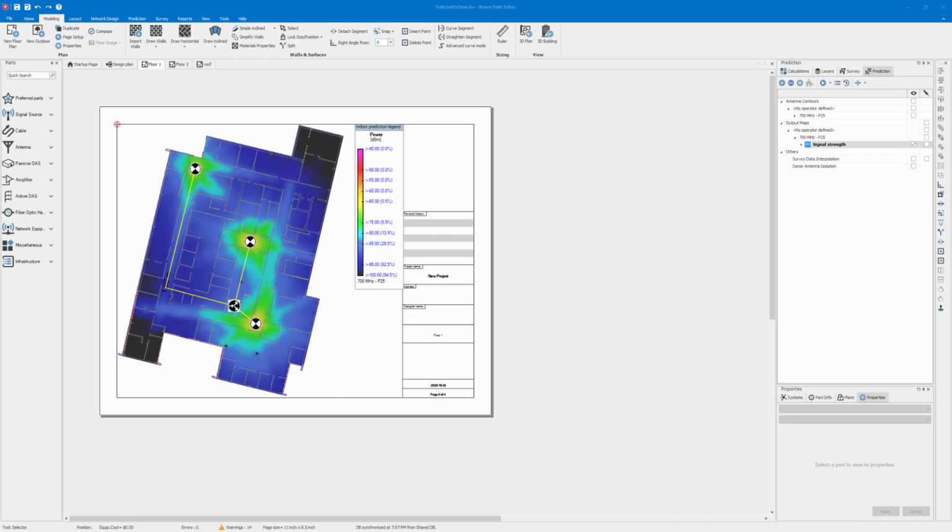As the name of the map says, this map will show you your uplink RSSI in a near-far effect scenario for every floor plan. What is the near-far effect? It's simply when you have a strong signal in your network, a UE standing close to the antenna per se, emitting a strong signal to the network, therefore activating the AGC to lower the output power.